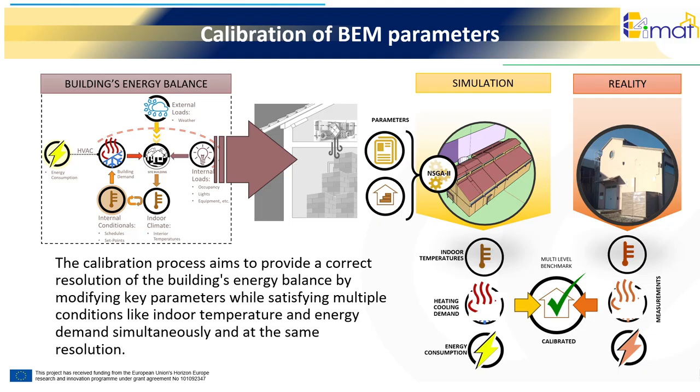The energy balance of a building and the interaction of its HVAC systems represents a complex problem filled with uncertainties. Various factors that contribute to the generation of thermal comfort and energy demands are related to variables of an indeterminate nature. Therefore, attempting to solve the system of nonlinear equations that defines the building's energy balance requires the introduction of assumptions and the estimation of certain key parameters in order to accurately simulate the building's real behavior.